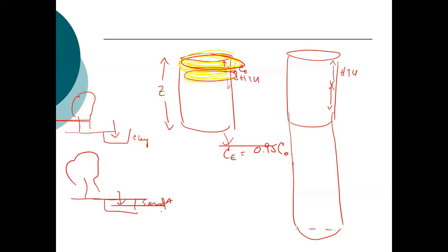The sand. The sand, larger grains, okay? And think too, back at the filtration, if instead we have coarse sand and fine sand, when we did those head loss calculations, how was head loss affected by the diameter of the particle? Wasn't it increasing with smaller diameter?